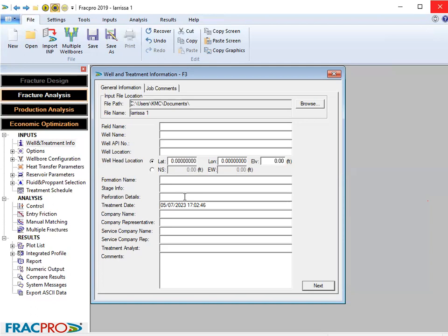Because before you do that, you have to first generate the IPR for a situation where there is no hydraulic fracturing. Then you see that the well is not performing well. Then after the hydraulic fracturing, you take all of these parameters and regenerate it for a hydraulic fracturing well. Then you see that the well is now performing higher, because you are going to have a higher productivity index and a higher AOF, absolute open flow, and all of that.